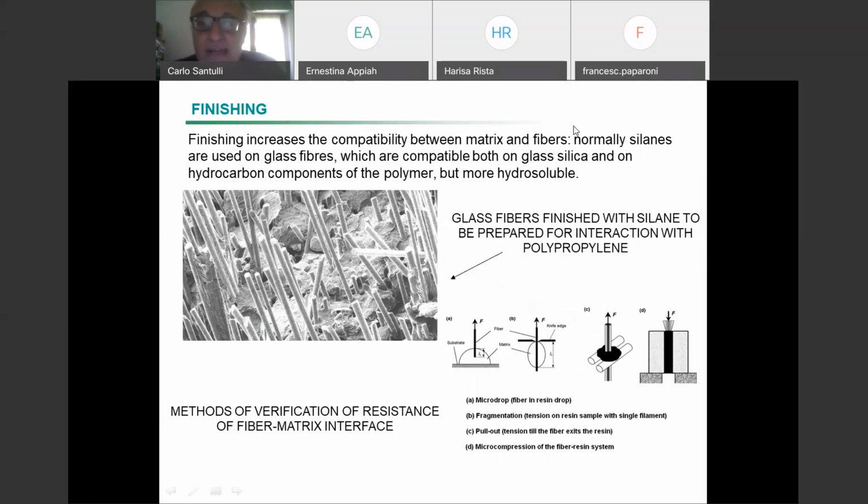Next time we are going to carry on discussing composites. Then we will have a diversion towards natural fiber composite applications. In our course it's both synthetic and natural materials together, because now there is no longer the time to do any distinction. We need to use synthetic and natural materials together, even in hybridization. We define hybridization not from the chemical point of view. Hybridization in material science means putting together two materials and making a further material which will work as one. So, for example, if you put flax and carbon fibers into a composite, you are making a hybrid composite.